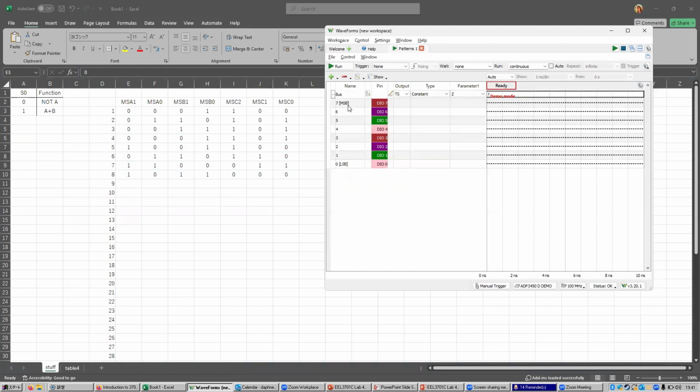You need to be very careful about getting the orientation of these right. You should at least know what DIO0 is going to, because it can get confusing with the endianness of it, like the order of these bits, high to low or low to high, but this is just something to look out for.